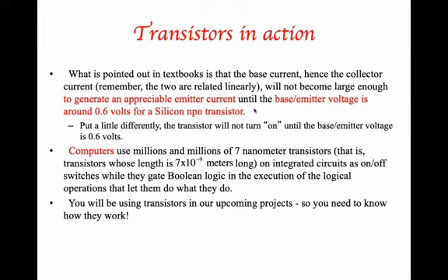Once the capacitor had discharged, the transistors would turn off, and then the solar cell would recharge the capacitor until the transistors turned on again, and then the capacitor would dump its charge through the motor. It's a very cool design. But the point is that it's using transistors like switches.